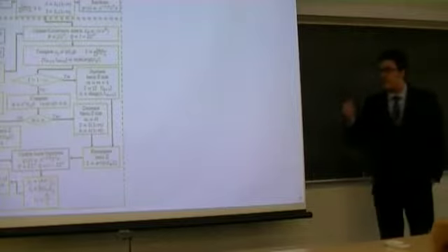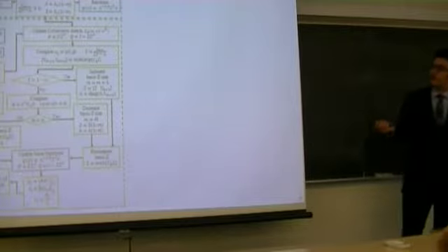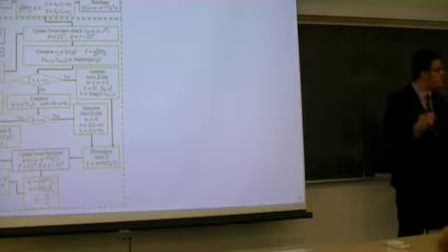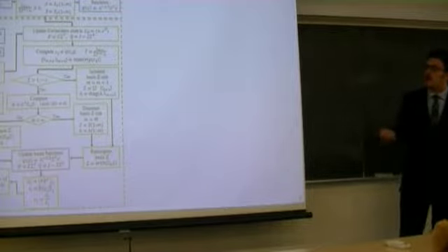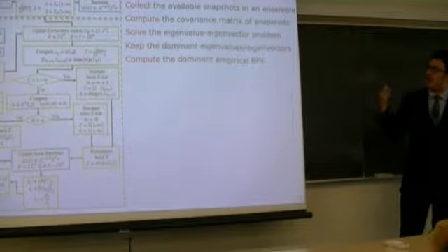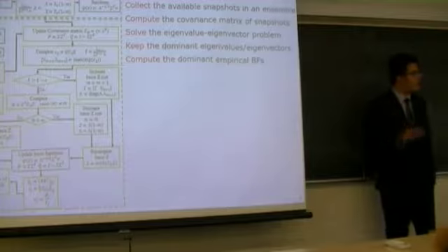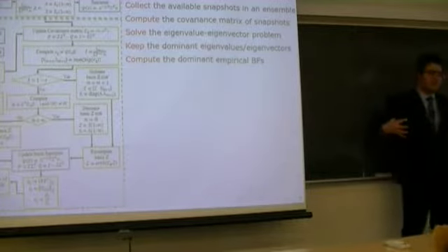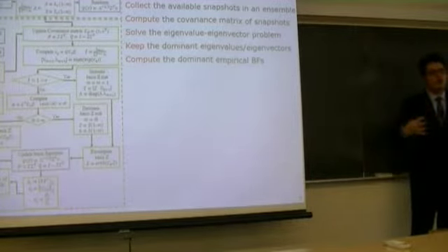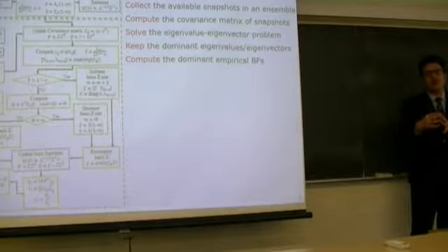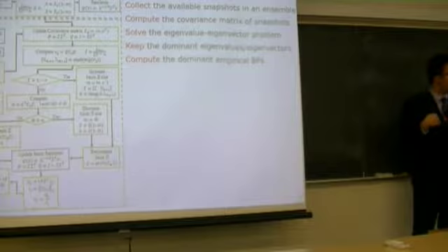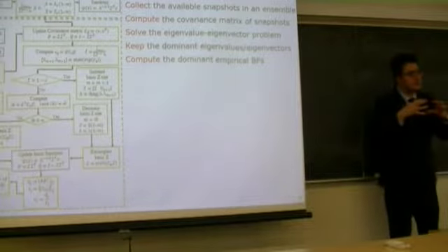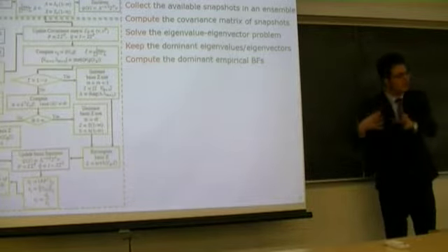So based on this idea, we developed an algorithm to recursively revise the set of empirical basis functions. This algorithm briefly has two major components, the offline step and the online step. In the offline step, just like the regular proper orthogonal decomposition, we gather the spatiotemporal data, compute the covariance matrix, identify the dominant eigenvalues and the corresponding basis functions, and use that as a basis to initiate the closed-loop operation.